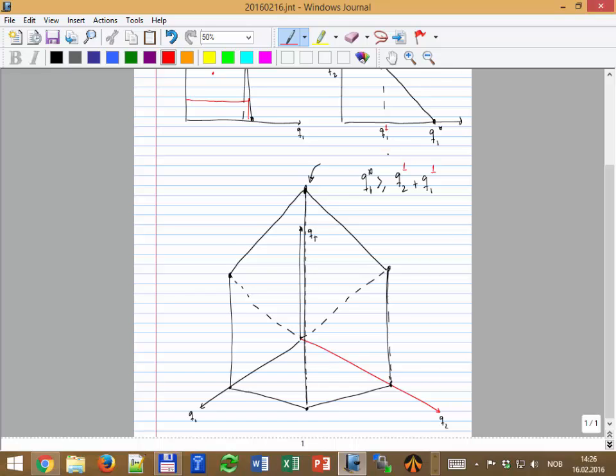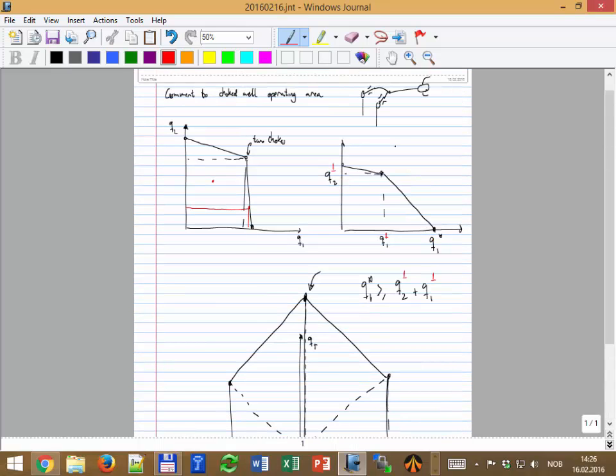You see that? So as I told you, we are going to have a separate session on optimization where we are going to discuss this issue more in detail. But just to let you know that not all the time when I just open the two chokes maximum, then I get full production. In this case, what is this telling you? That well 2 actually doesn't produce much, but creates a back pressure to well 1. It kind of inhibits him from producing more.